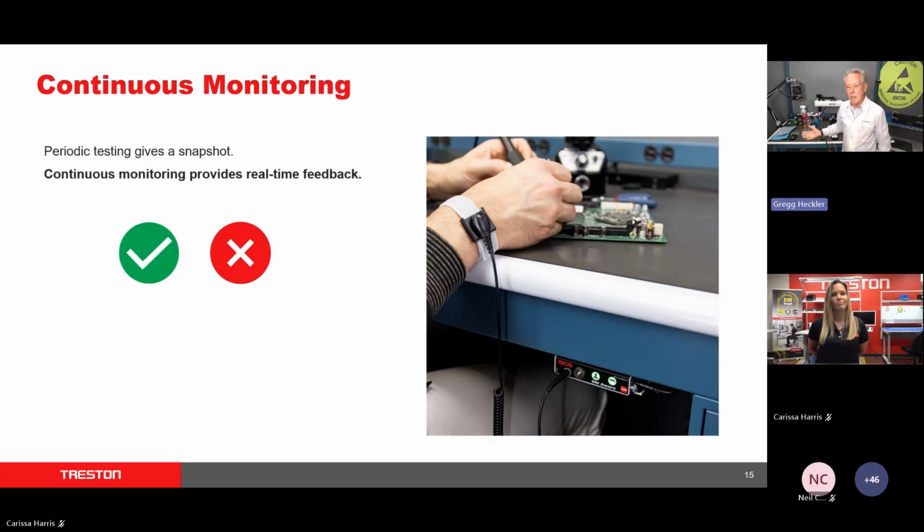So at a typical electronics manufacturing company, they do what we call touch testing, where we walk over to a wall. In fact, I got one right here. Here's a classic integrated checker, or sometimes we call these touch testers. I walk over, I plug my wrist strap in, I press the button, I get a green light, write my name down that I passed, and I go to work. The problem with that is, one, it's a total trust thing, right? You're going to assume that somebody's writing pass on there and they're going to work. And then you're probably not going to test again until you come in the next morning or 24 hours later.